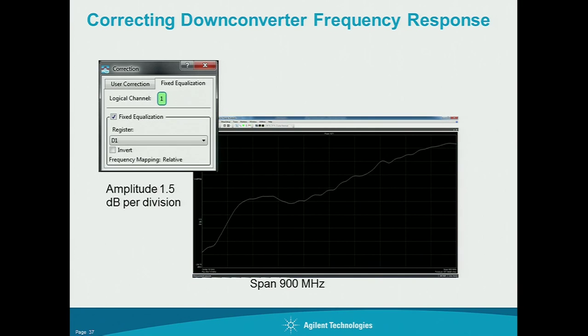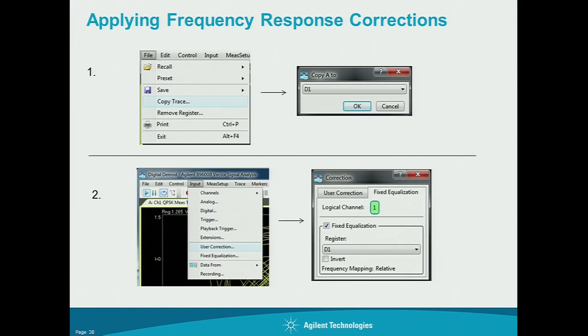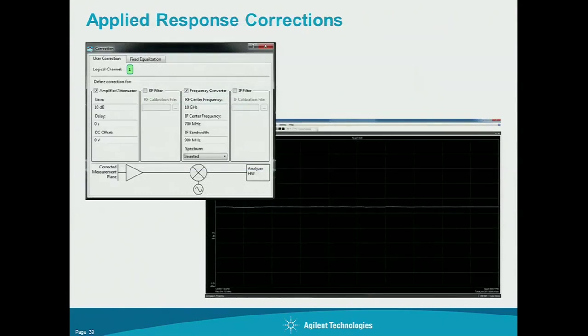That's the frequency response, essentially, of the IF of the down conversion process. You invert that, and you apply a correction, and now you have a flat, nice and linear response where you can make a more linear and equalized measurement at a much lower cost than maybe going directly into a really wideband oscilloscope.